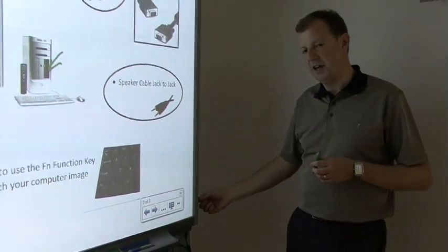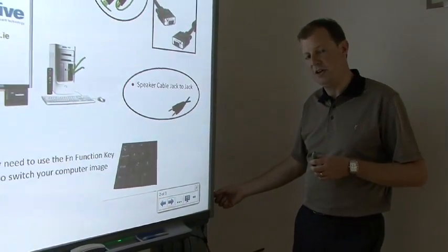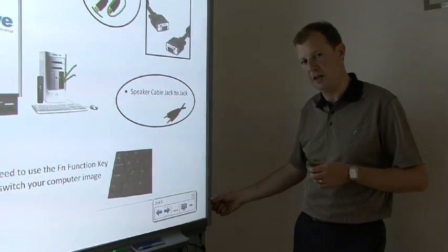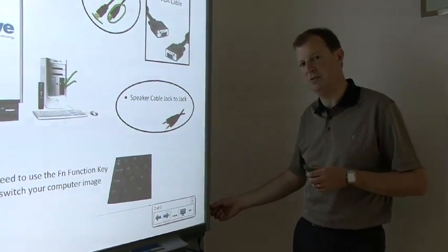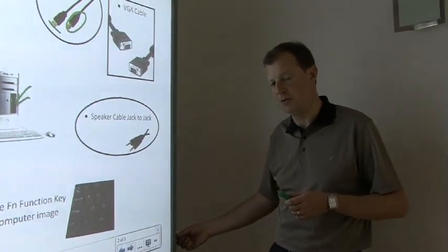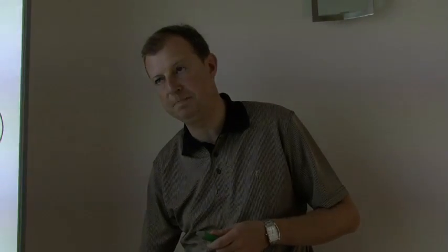This little flicker light at all times should show a constant green colour. If for whatever reason you don't see a constant green colour, it might be red or it might be flashing green, you know that then there is an issue that needs to be addressed. Your first port of call should be to actually check the USB cable at source and just make sure that it's connected at both the board and equally at the USB port on your laptop or desktop.